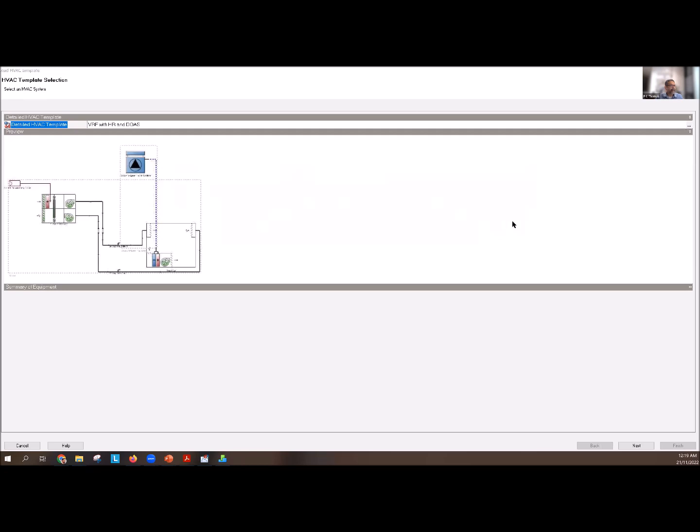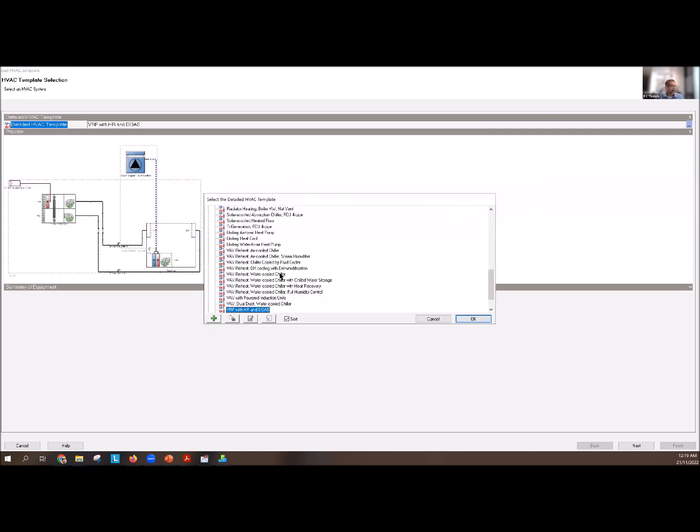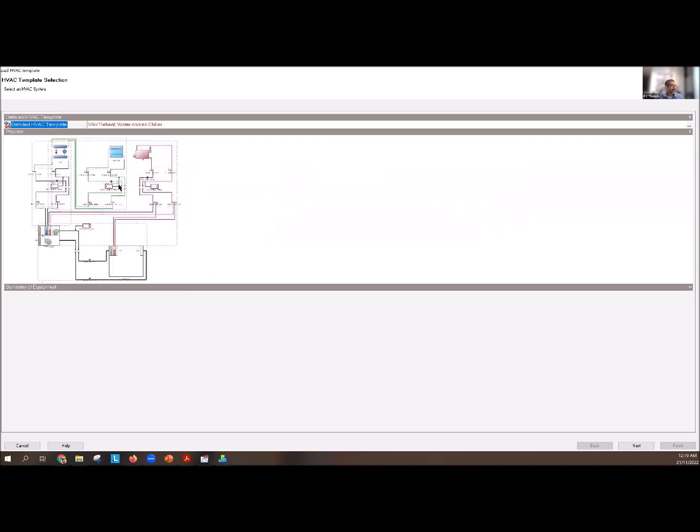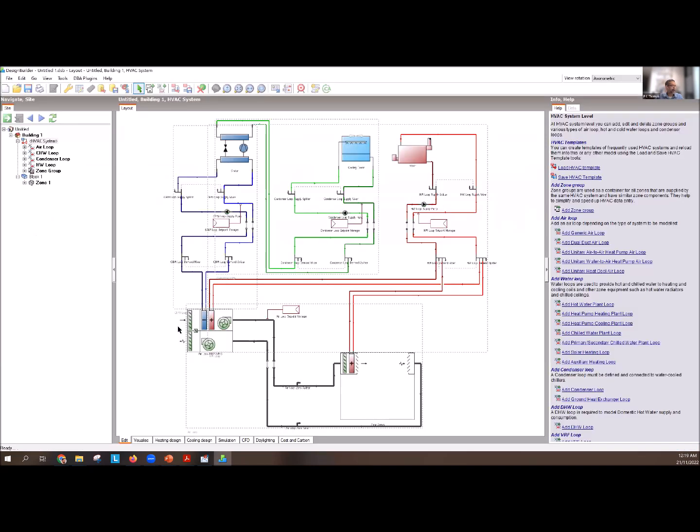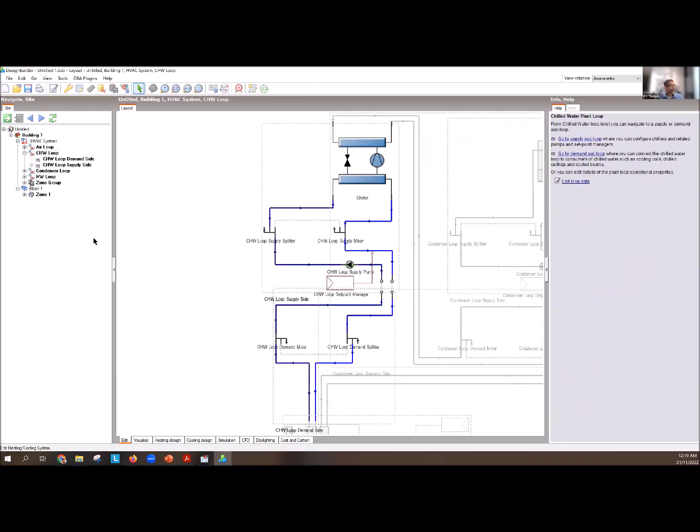You can do fairly complicated air conditioning systems. So I'll just put in a complicated one. This one here is not an appropriate system for this small building, but you can see there's a water-cooled chiller and cooling tower that supplies a cooling coil inside an air handling unit. The air handling unit has a supply fan, return fan, controller, VAV box. So there's a lot going on which you can look at. And it's all possible if you know what you want to do.